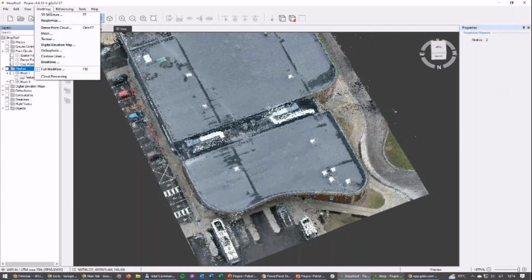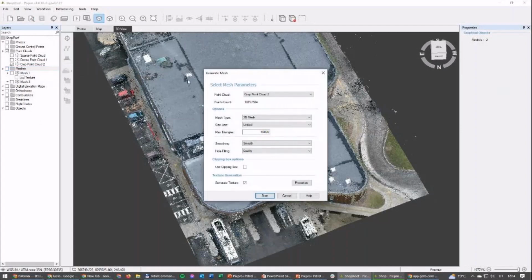When you are generating mesh for PVSol, the point to remember is that PVSol does not support a big amount of triangles. Our software can easily generate a mesh with about 2 million triangles, which is way too much for PVSol, and you really don't need that because we are looking at a lot of flat spaces anyway.